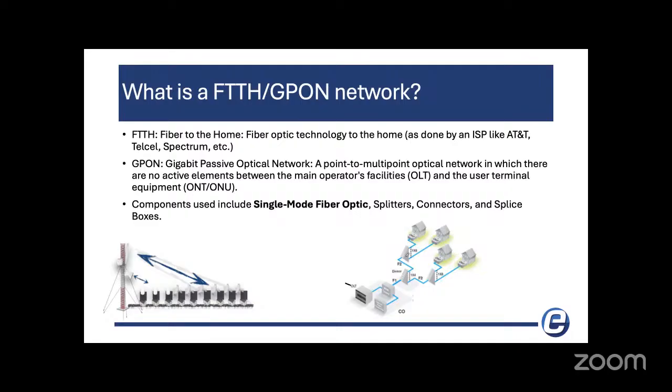So it splits off and it splits again and it gets to another active device, which will be your ONT or your ONU. For this type of installation, single mode fiber optic is what we recommend, because there are long sections and single mode will give you the most range.